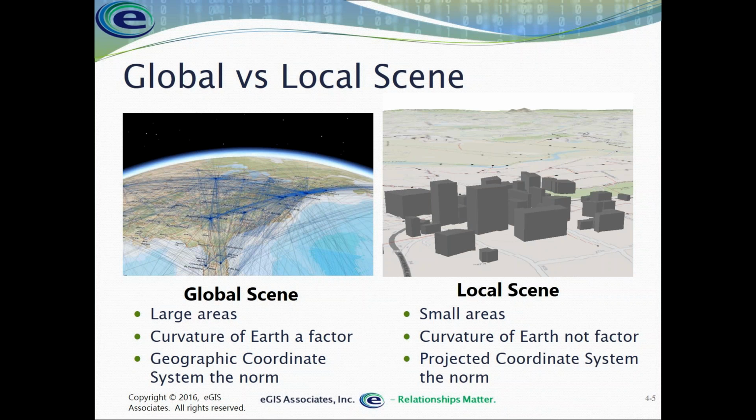you could even use the WGS 84 Web Mercator Auxiliary Sphere if you were going to publish this to the web, which is possible through ArcGIS Pro with ArcGIS Online or Portal for ArcGIS, to publish 3D maps to the web to use in applications, either mobile or web-based applications, right? And so you'd want to use that auxiliary sphere or coordinate system if you were to do that.